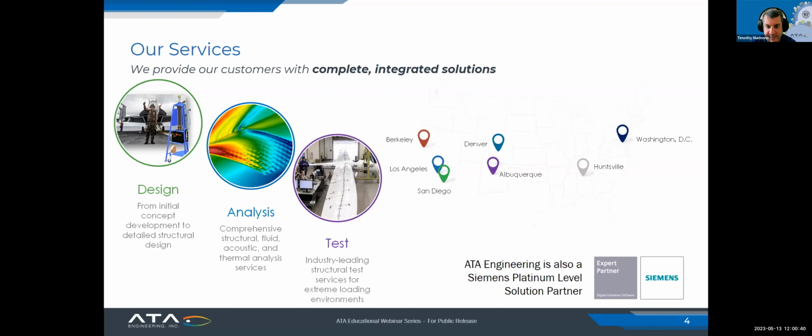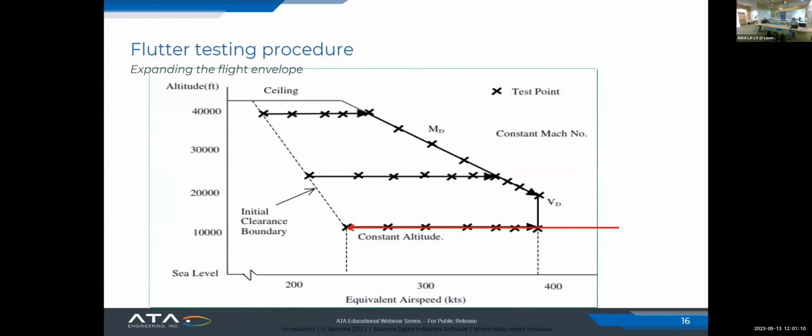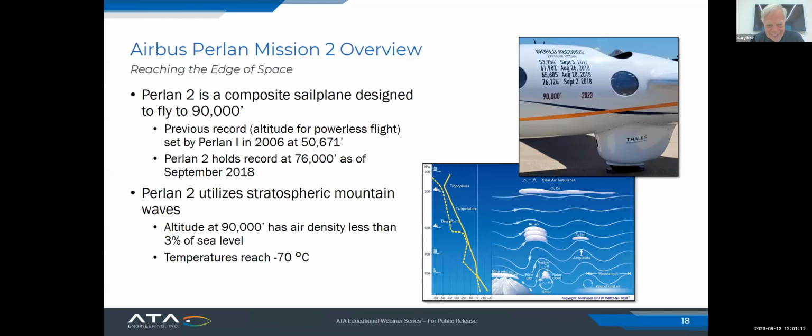Yeah, I think I agree with that. And they're not necessarily thin. Sorry, go ahead. I was going to say, with high aspect ratio vehicles, at the root the wing airfoil is probably not that thin. If you look at the Predator, those chord thicknesses are 40, 50%. They're pretty fat wings. Structures guys like that. Makes our life easy. Big torque box, tall. Yes.